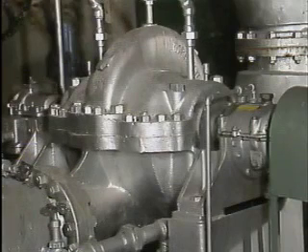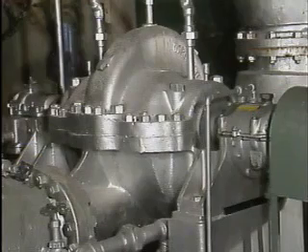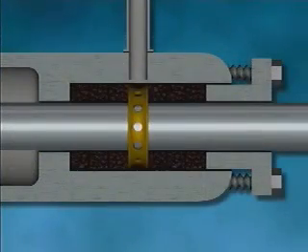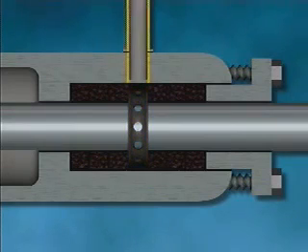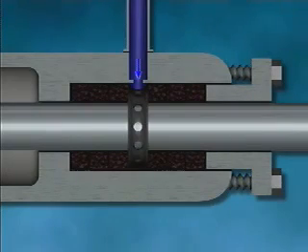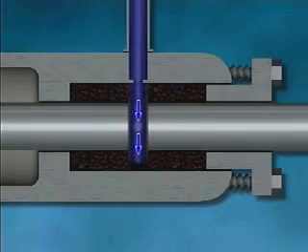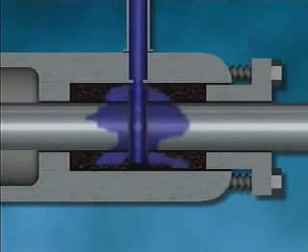Certain applications, such as pumps, generate more friction than others and require this additional fluid to keep the heat that builds up under control. The lantern ring is always positioned under a line called the gland seal line. The gland seal line directs liquid, called seal liquid, into one of the holes in the outside edge of the lantern ring. The seal liquid flows around the lantern ring and through the holes in the ring, where it's then distributed into spaces around the packing and the shaft. This flow of liquid helps keep the packing cool.